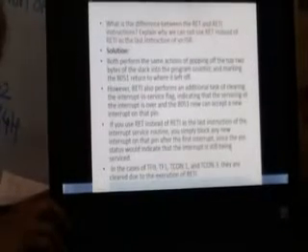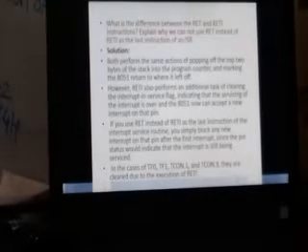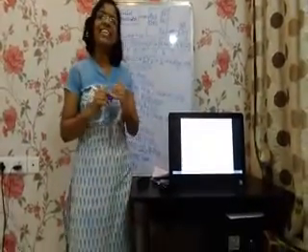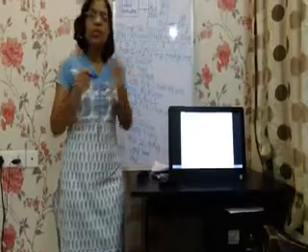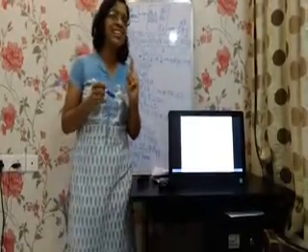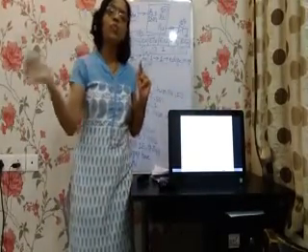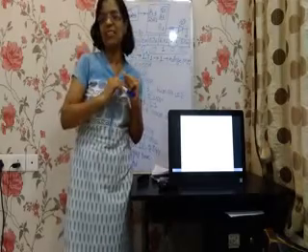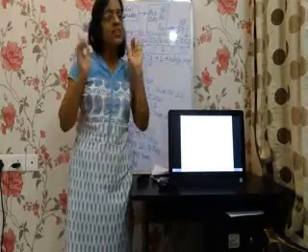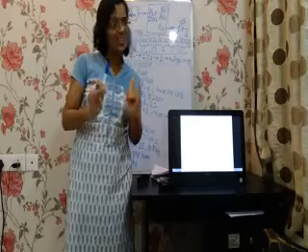Now there is a very basic question. What is the difference between return and return on interrupt? They both look similar. What are RETI and RET? We know the function of RET. What happens when RET is executed? The control goes back to the place where it had left the execution in the main program. The same function is performed by RETI also.